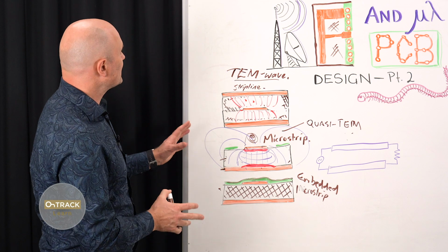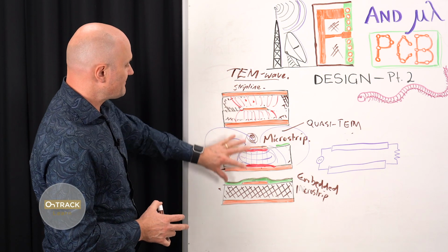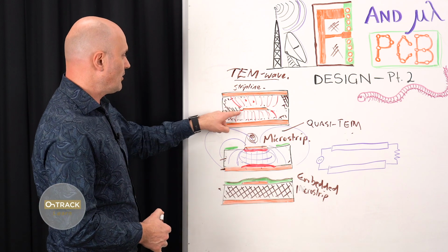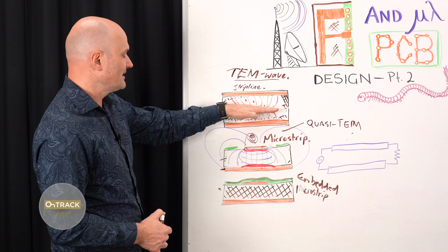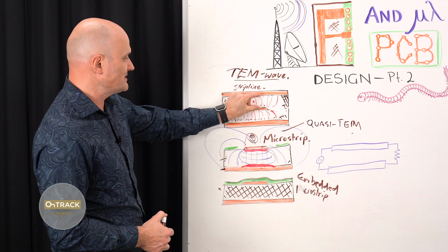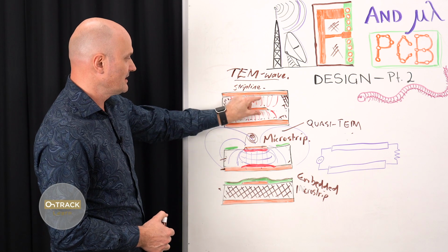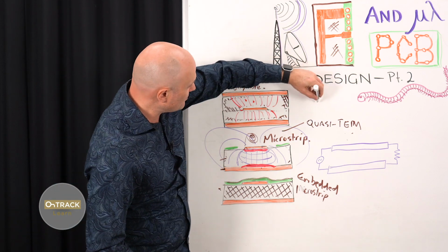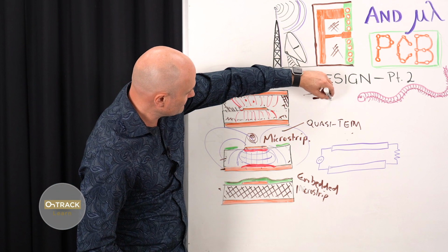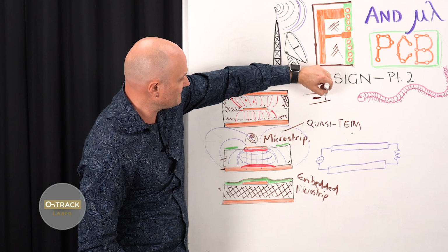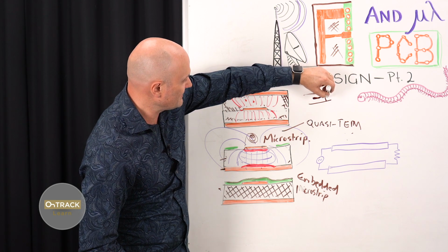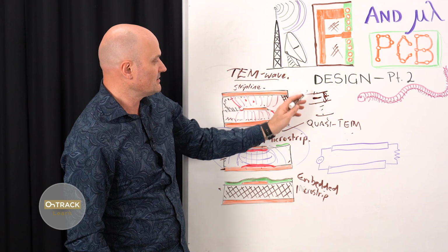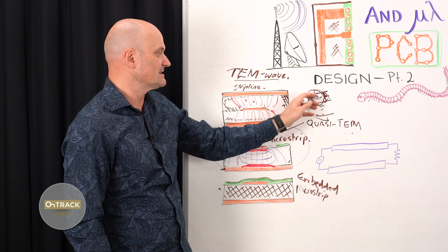Okay, so not to get too far ahead of myself, but these are the fundamental types of transmission line you'll be dealing with in a printed circuit board. And if you're wondering how to get an exact stripline, which has the same distance on one side as the other, typically this is part of a multi-layer stack where your PCB stackup will have stripline, plane, plane, and you'll have the same distance of dielectric above and below the stripline, and then you'll have some other layers and planes, and you build it up as part of a multi-layer PCB stack.